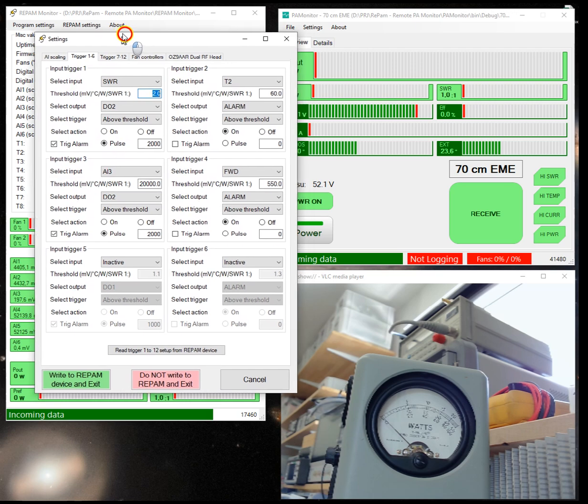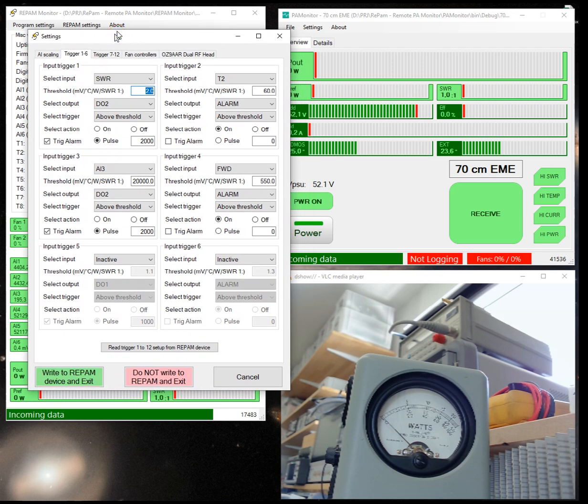The reaction time for this to happen has to be pretty quick in order to hopefully avoid burned LDMOS and so on. And when monitoring the SWR, the moment from when the high SWR condition is seen until the relay contacts of the relay it's controlling have closed, effectively closed at 0 ohms, it takes 2.3 milliseconds.